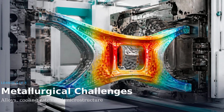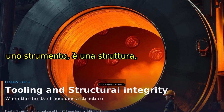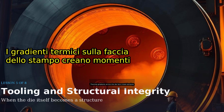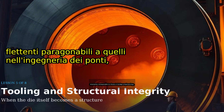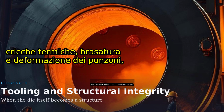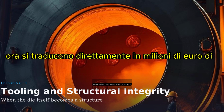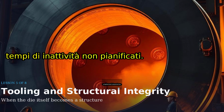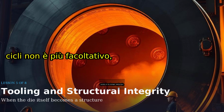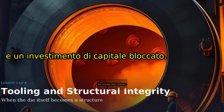At megacasting scale, the die is no longer a tool, it is a structure. Blocks weigh over 100 tons. Thermal gradients across the die face create bending moments comparable to those in bridge engineering. Heat checking, soldering, and core pin deformation, which used to be maintenance nuisances, now translate directly into millions of euros of unplanned downtime. Predicting tooling behavior over hundreds of thousands of cycles is no longer optional. It is the difference between a profitable line and a stranded capital investment.